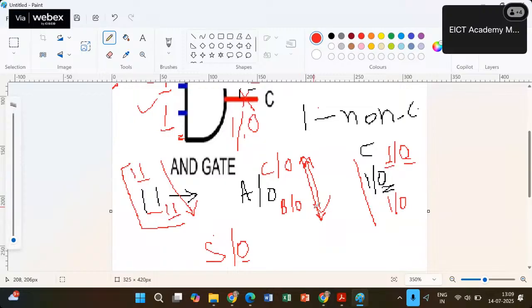Now, generally the output fault we have to remove. The reason being inputs we can control. Input is in our control. So inputs, we will try to push the faults towards the inputs so that it is easy to push that to 1 or 0 very quickly, right? I cannot expect that in a complex circuit output can be 1.